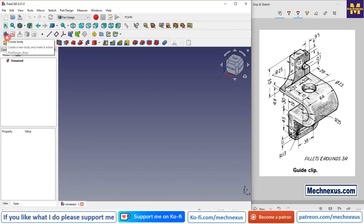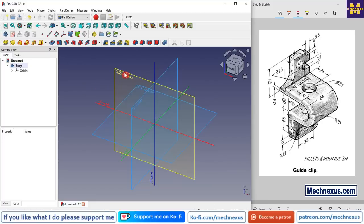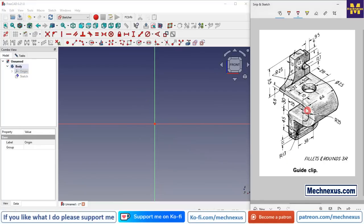So I will close this file and create a new file, and here I will create a body. I will turn on my origin planes, select the front plane and click on the sketch, go to the model tab, and hide my origin planes. Now this will be our base feature, and this edge will lie on our axis.